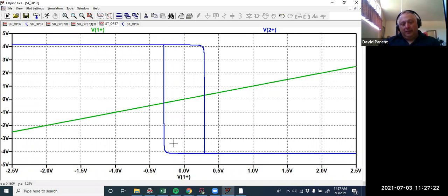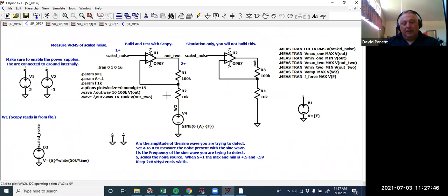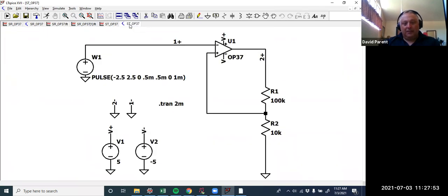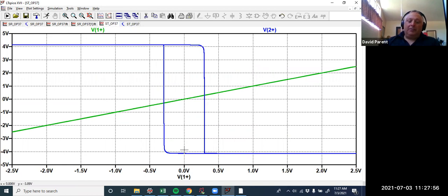And so now if I have noise superimposed in time, and I'm just bouncing my cursor around, if the noise is too small, it won't switch one way or the other. And if the noise is too big, it's just switching all the time. So the sweet spot is near these peaks. Same thing with the sine wave, right? This sine wave, if it's too big, it actually is just turning this thing off and on without stochastic resonance, okay? So the amplitude of the sine wave itself has to be below this hysteresis width, right? But yeah, the larger it is, the easier it is to detect.